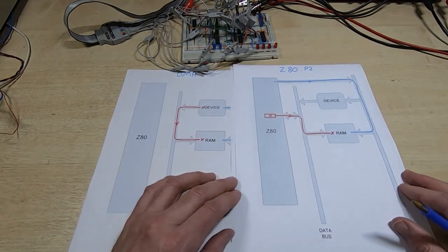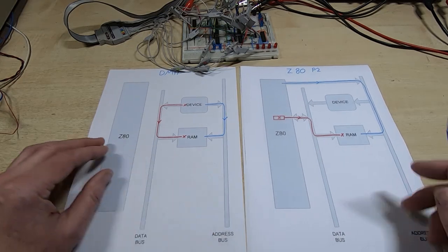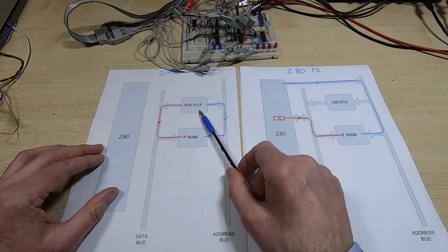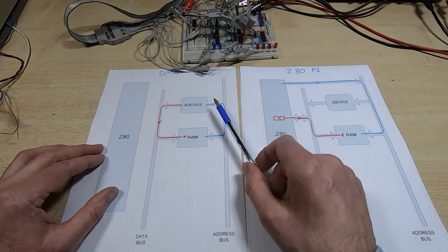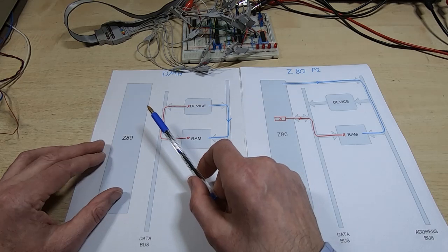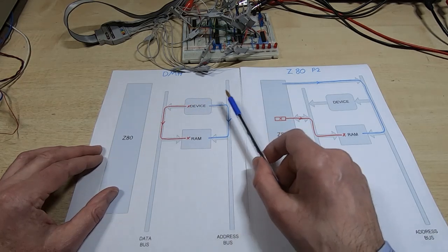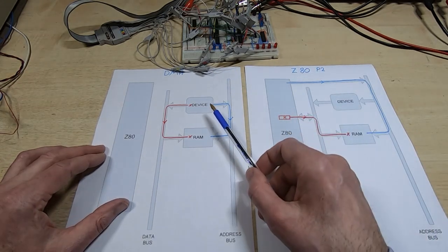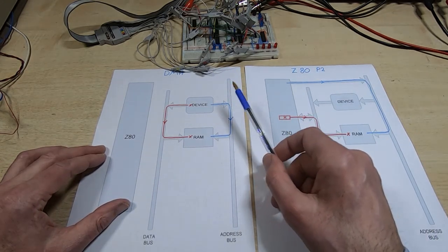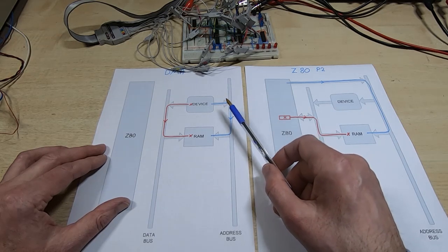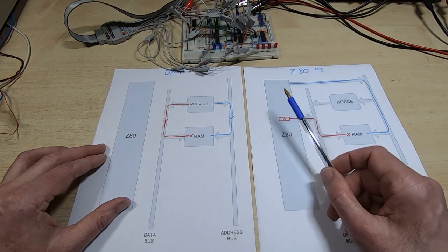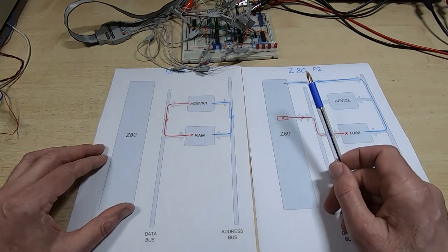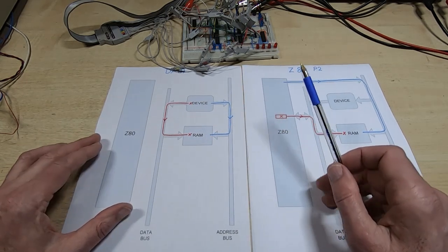Now if you're not intending to implement DMA, then it's best not to use in-out operations to access your device, simply because the Z80 automatically inserts wait states into the in-out instruction stream, so it tends to slow it down slightly. If you use mapped memory addressing instead, then it will of course save a few microseconds for each bus cycle, so it does save some time.